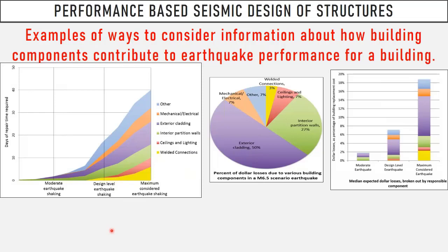And what you have at the end, for instance, for different levels of earthquake, for different levels of non-structural components, like mechanical, electrical, exterior cladding, interior partition walls, ceilings, and others, is what repair time is required. And you may have an idea, totally you have 40 days, for instance, which component has the most effect on this? And which component is the critical one?